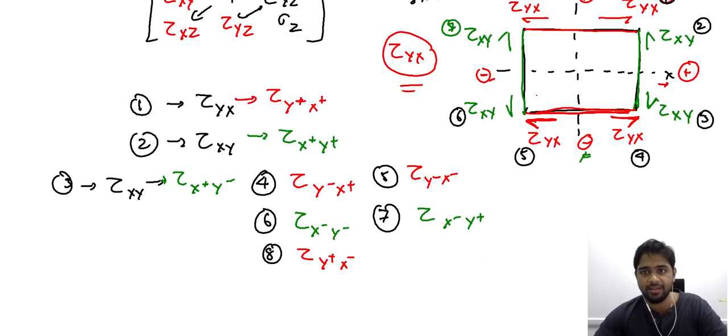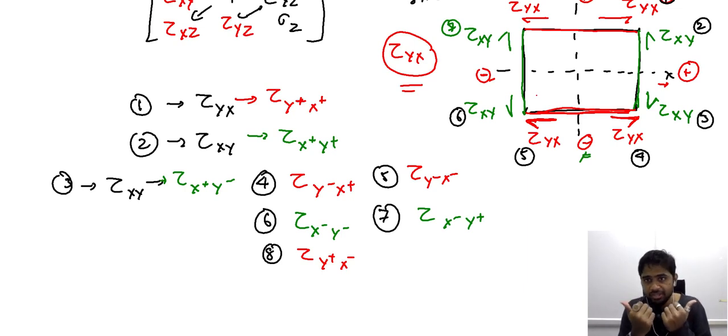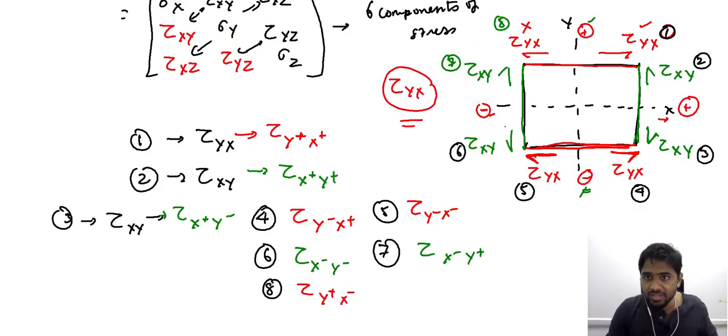So what we have done is, we have now used appropriate notation to include the difference in the direction associated with the shear stress. When we just had two subscripts, we were not able to distinguish the different shear stresses, those acting in different directions and those acting in different planes. So stresses 1, 4, 5, 8 all had the same description, and all the other stresses as well.